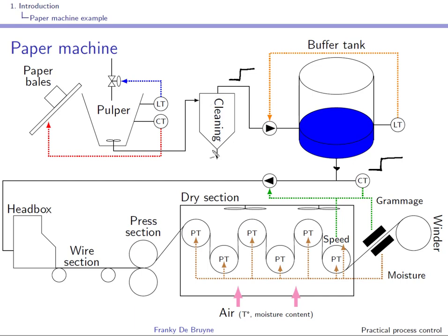But remember that your cyclones will operate best when you do not have any sudden flow changes. So this is not something that we desire. We would like to see something that is smoothed over a longer period, something like this, so that this change is propagated over a longer period and you do not have these sudden stock flow changes through the cleaning stages.